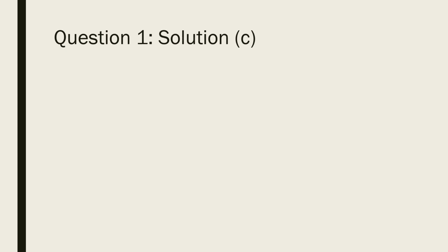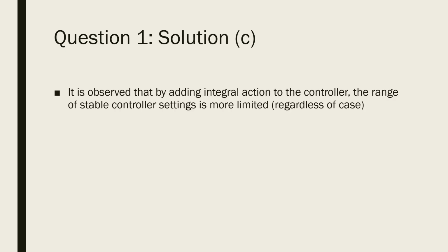Regarding the stabilizing effect of adding the integral action, we notice that the stable region for controller settings becomes more limited when we add integral action, regardless of the case whether LHS is positive or negative.